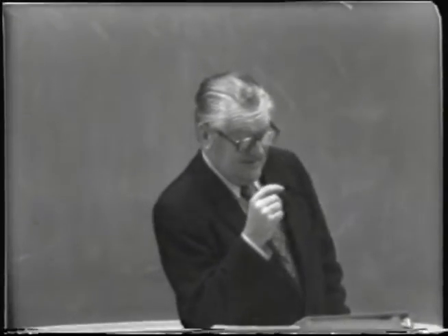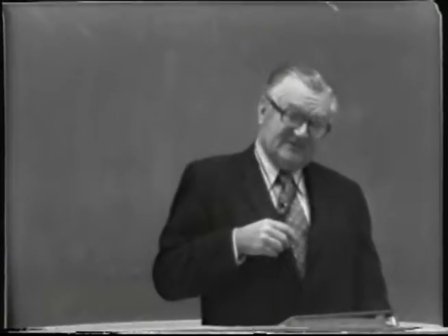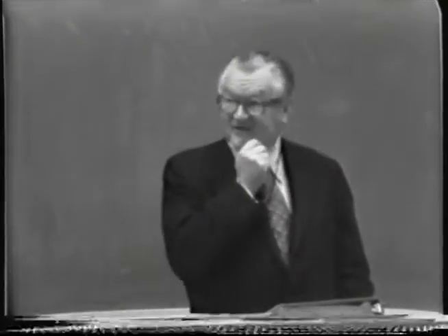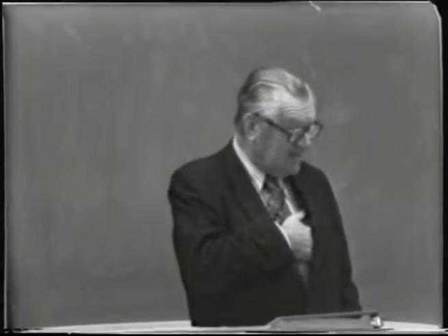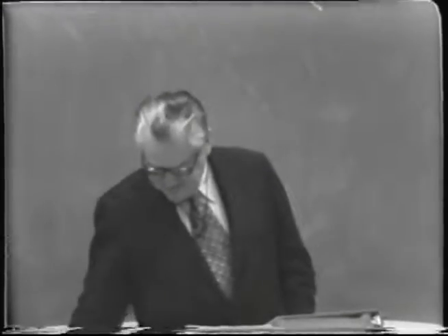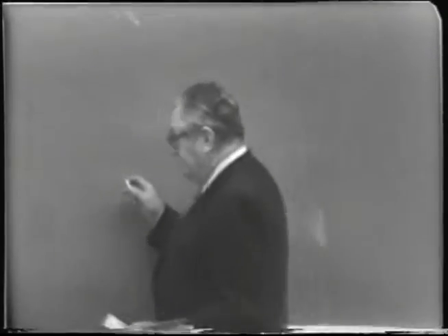Now, there's one point about this that may be a little bit confusing, and that is you could argue with me about one plus or minus one ideal stage at times, because if I ask you how many ideal stages are required, that is really one stage more than the number of ideal trays, because the pot is a stage. Perhaps if we made a little sketch here again of a hypothetical situation, we might visualize this better.